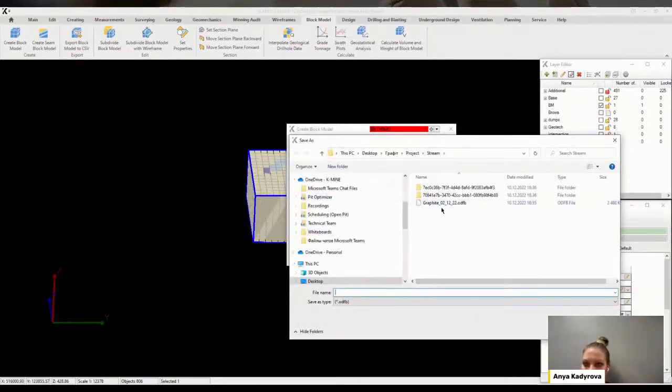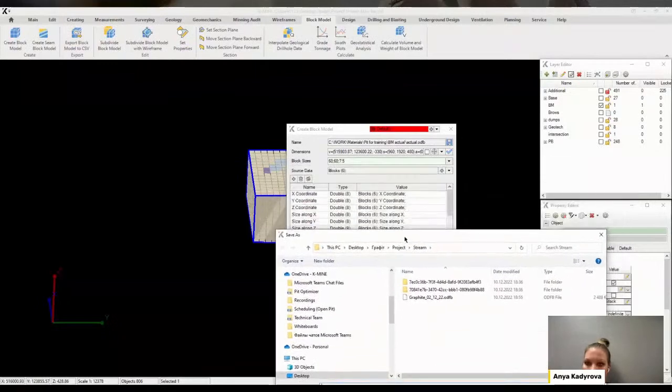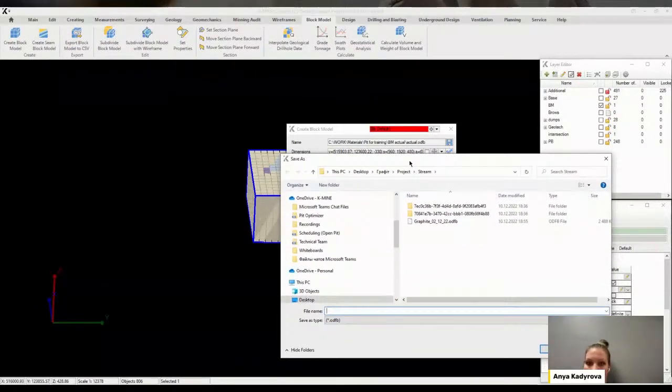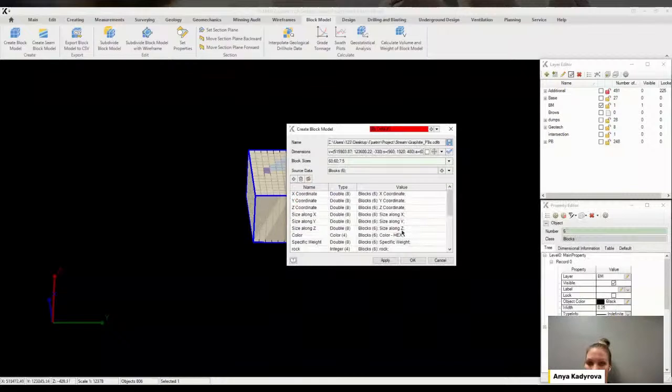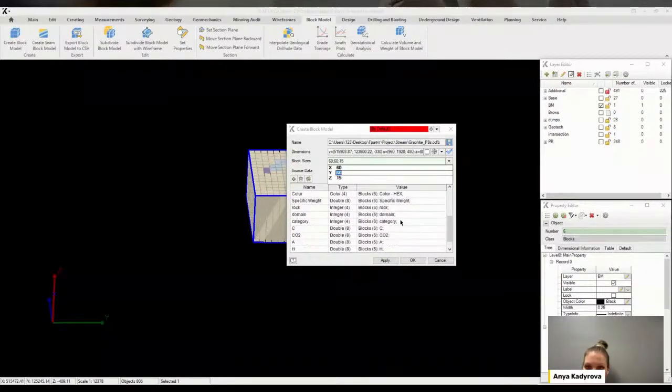type, and also for the convenience of using block model in the schedule model, we can combine block model blocks in height. In the original block model, they are 7.5 meters, and we indicate 15 meters. Quality also will be recalculated as a weighted average. The updated block model has been created and placed in the base layer, from where it can be moved to the desired location.